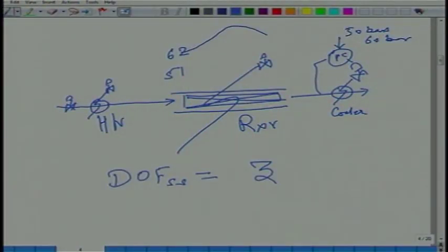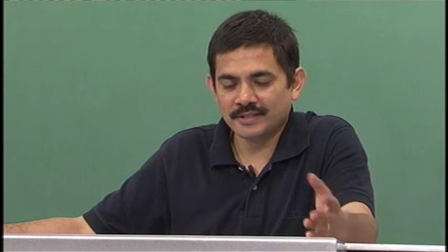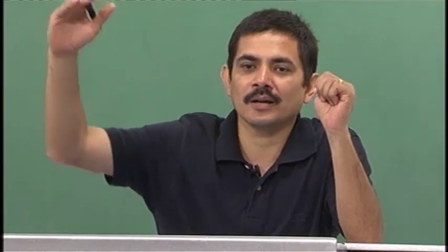I can complicate it a little bit more, but okay, now let me get to economics. If you are running this reactor, would you like to run it at a low pressure? Why? Low conversion, reaction rates would be smaller. Okay. So, once the reactor is designed and it is designed to operate at a maximum pressure of, I do not know, let us say x bars, you would typically operate at x bars.